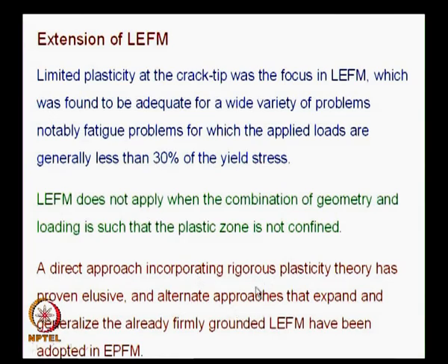and people were looking at what are the alternate approaches, and in those approaches what you really want to do is, you have already learnt concepts related to linear elastic fracture mechanics, how these concepts could be modified and adapted for elastoplastic fracture mechanics. So, what you will find is, like we have looked at energy release rate, we will also look at energy release rate, and we have looked at R curve, we will also look at J curve here.